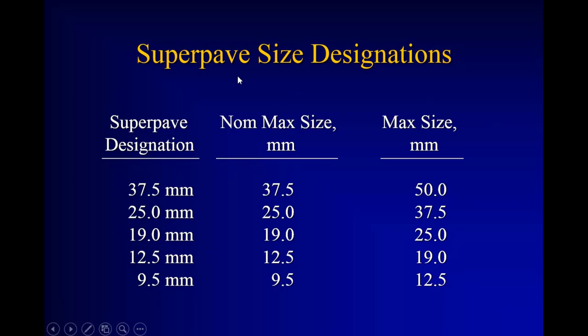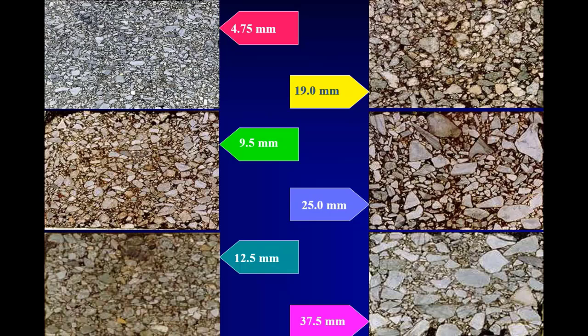The other unfortunate Superpave designation, when it first came out in the early 2000s, a lot of states thought, oh, then we got to have a lot of large stone mixes. And these are mostly quarry states. And boy, was that a misconception, because large stone mixes are very hard to compact and very hard to work with and can be very expensive. So here's just some cutouts of some gyratory plugs or pavements with the different nominal maximum aggregate sizes. And typically in North Dakota, this is what we're looking at, this 12.5, whereas you go over to 1.5 inches or 37.5, you can see large stone mix.